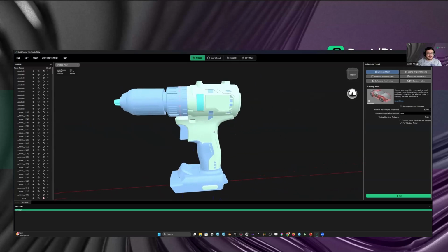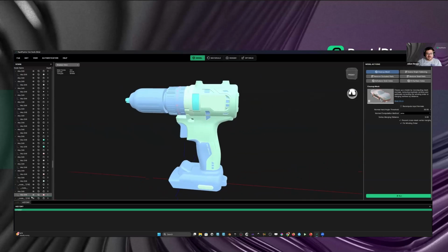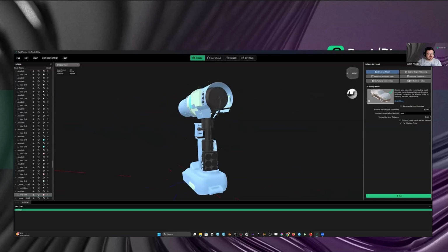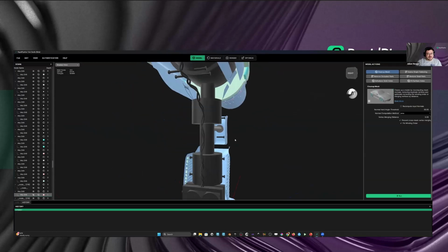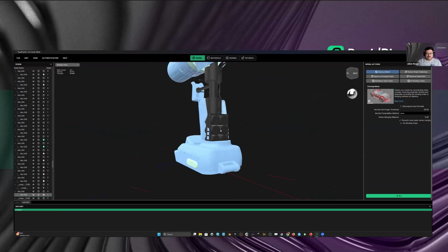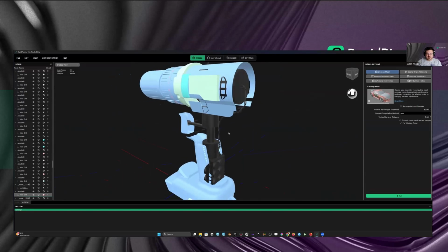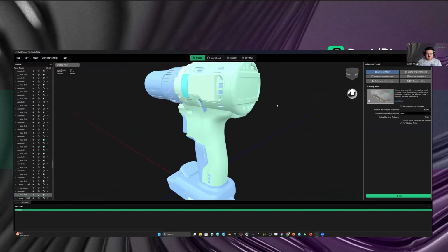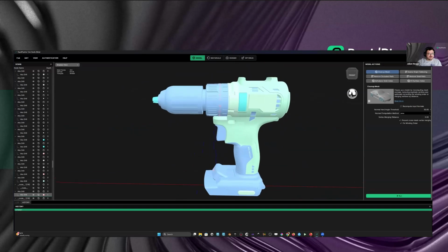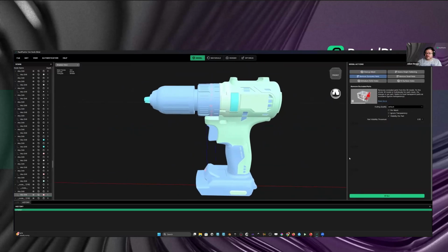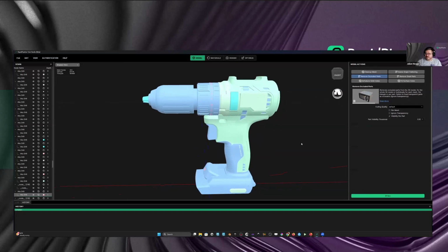What we have here is that drill file, and let me just blend out this node. You can see here in black is all this cable running, some batteries down here. So there's a lot of interior stuff going on. To remove that, it's as simple as using the remove occluded parts action, which is already here. I could have used it on import, but I just want to show you a couple of the settings inside the actual operation to better illustrate what it actually does.